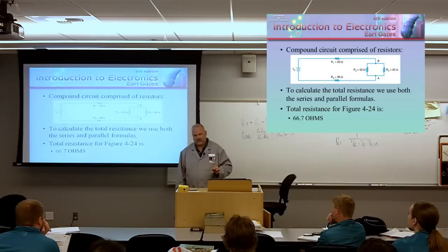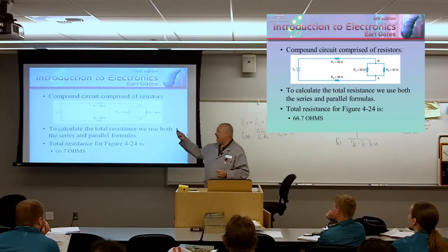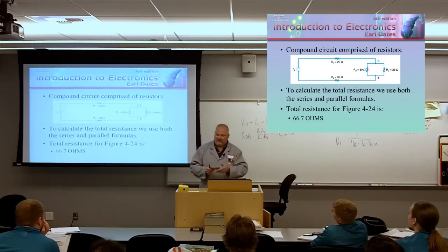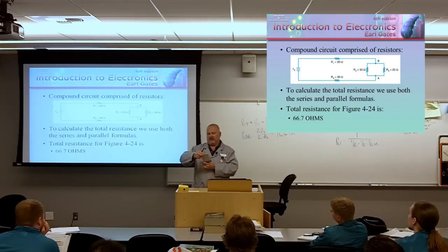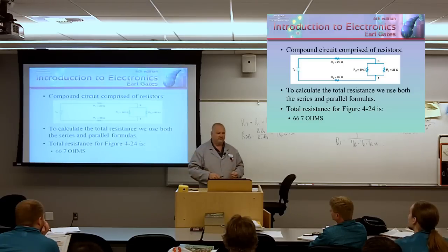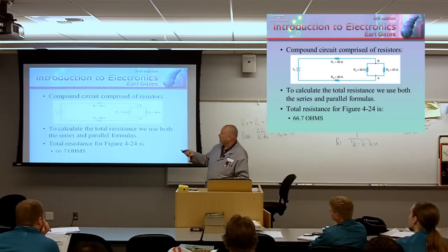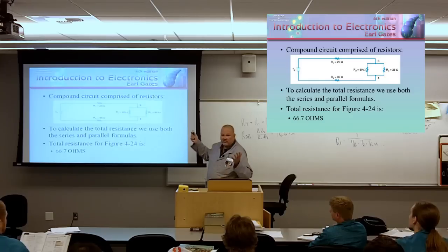If you could do that in your mind looking at this stuff, I want you on my team. I'll be honest with you. Those are the people that I want. If I give you this problem and immediately you're with the calculator, and I don't mind if you use the calculator, but if you're turning it upside down and sideways, no. What I want out of all of you is to look at this. I got 30 ohms here, I got 20, that's 50. 50 and 25, less than 25, my answer is going to be less than 75 ohms.